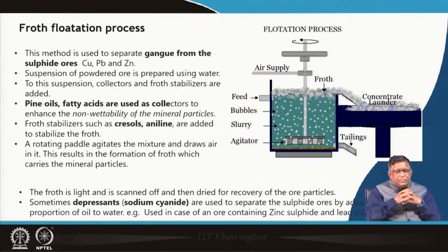When you add a collector such as pine oil or fatty acid, what do they do? They enhance the non-wettability of the mineral particles, so that the particles have no affinity to the water and have a tendency to go to the froth.